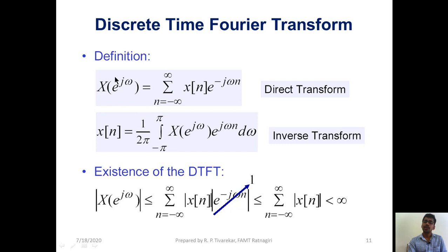Its discrete time Fourier transform is periodic, and minus pi to plus pi is a unique range in the digital frequency domain. After that everything gets repeated. So X of e raised to j omega is a periodic and continuous function of frequency. As it is a continuous function, we need to integrate it instead of using a summation sign. And as it is extended uniquely from minus pi to plus pi, we use minus pi to plus pi. And this is a scaling factor 1 upon 2 pi, which obviously comes. For that we have to see a derivation, which I am skipping here.